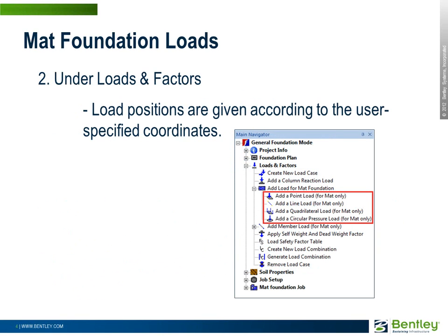The second method to add mat-specific loads is by selecting the desired load under Loads and Factors in the main navigator. Load positions are given according to the user-specified coordinates. I will briefly go over creating all four types using this method.